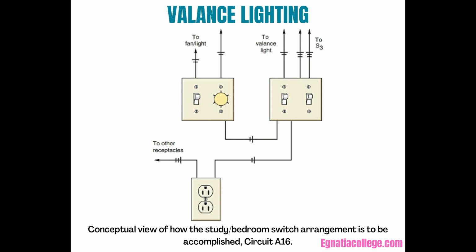Since this room is intended to be used as a study or home office, a personal computer will probably be located here. Since the study has switched receptacles in this room, a TVSS bar will be used to connect the power for a personal computer on the constant power section of the receptacle. The wiring requirements for telephone and data systems are discussed in Unit 23.